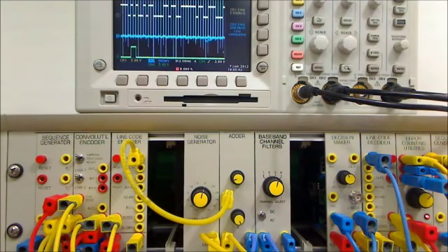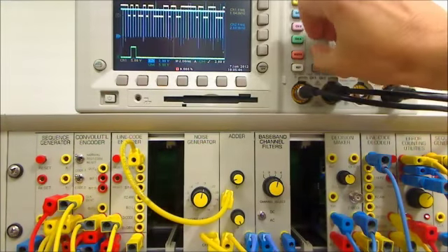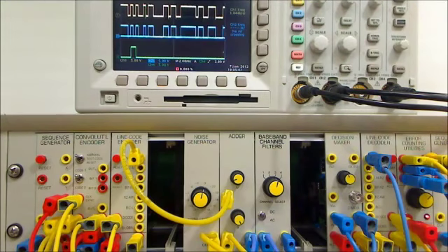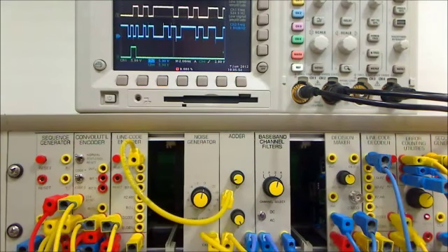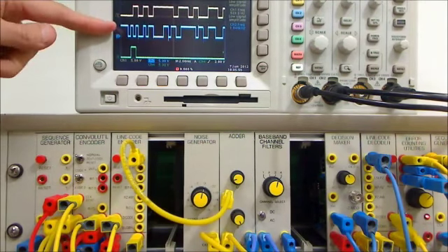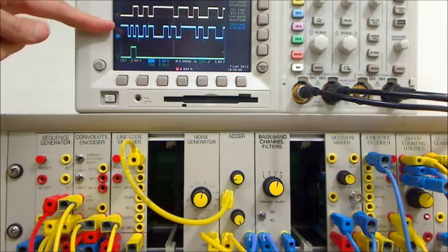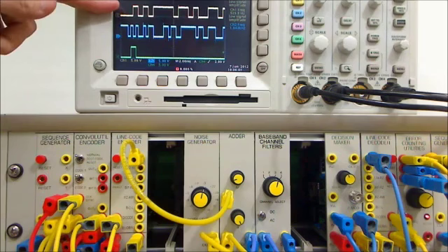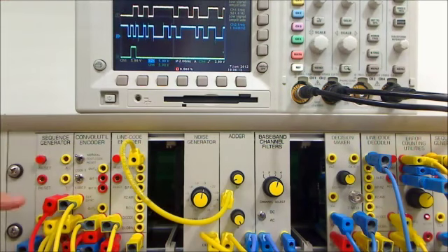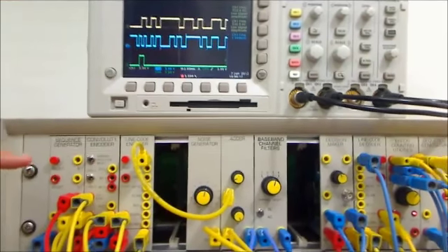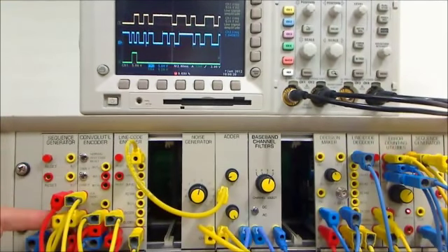Okay, turn the voltage range down, that's the clock. We'll look at the data going in. Okay, and now you can see the signal here, the blue signal, is the data going into the convolutional decoder, which is implemented on the TIMS DSP card, and the orange signal is the data coming out of the convolutional decoder. So that ought to be the original signal coming out of the sequence generator, but way back here.